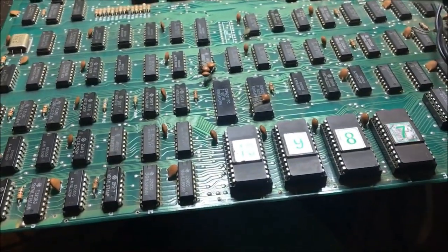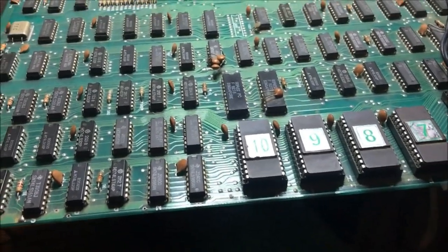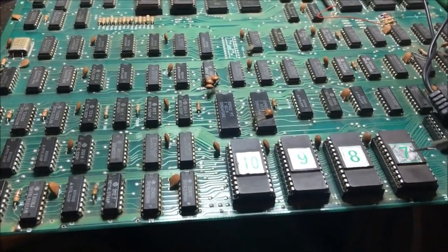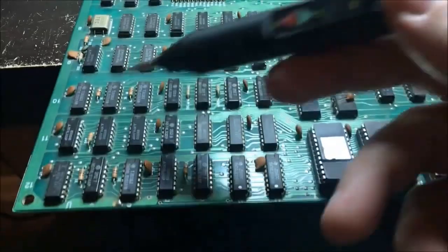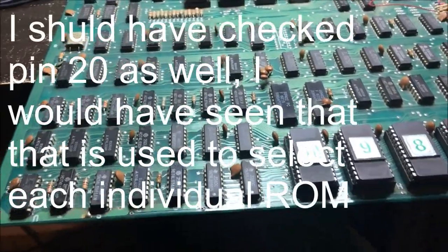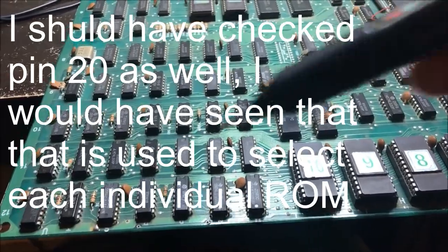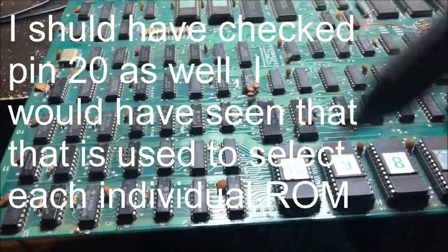So these are not being accessed correctly, and that's definitely a place to start, to trace back what is controlling these. There's some kind of logic over here or over here. I don't know. I have no schematic for this board, but I'm going to trace back the control lines and see what is dictating what gets accessed.